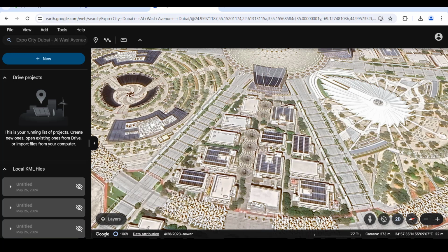If you do not do that, it may look right when linked in your main file, but when you link these two files independently, this file will sit in a different direction in context to the other file. You will get a wrong direction. You will model your cable here, and once you go and link in the federated model, your building will sit elsewhere.